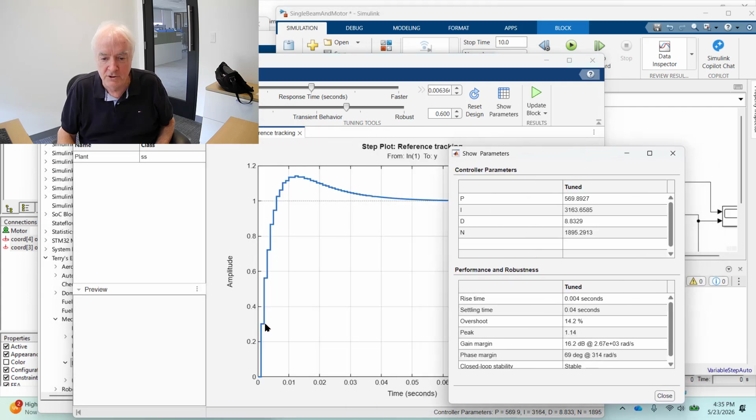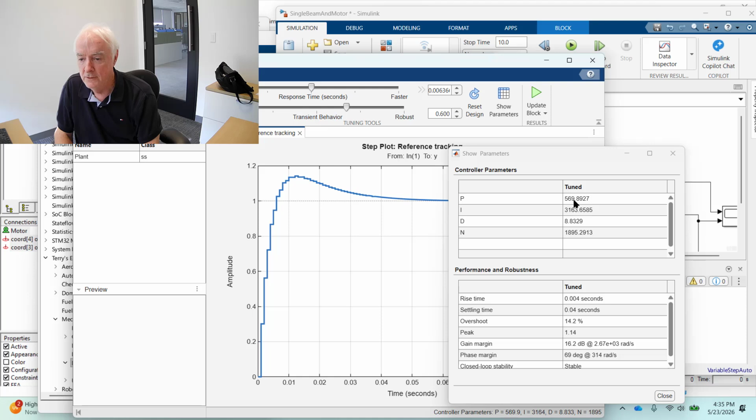I like this image because it's really getting at what we really mean by discrete, which is, at each point in time where we sample, and sample is make measurements of angles, but also assert the new torque, that the torque being received kind of looks like this. It's kind of got the staircase nature to it. And let's see, notice this. I can't even click on it anymore. And so these values are probably about 10% of where we were. So let's go for it.